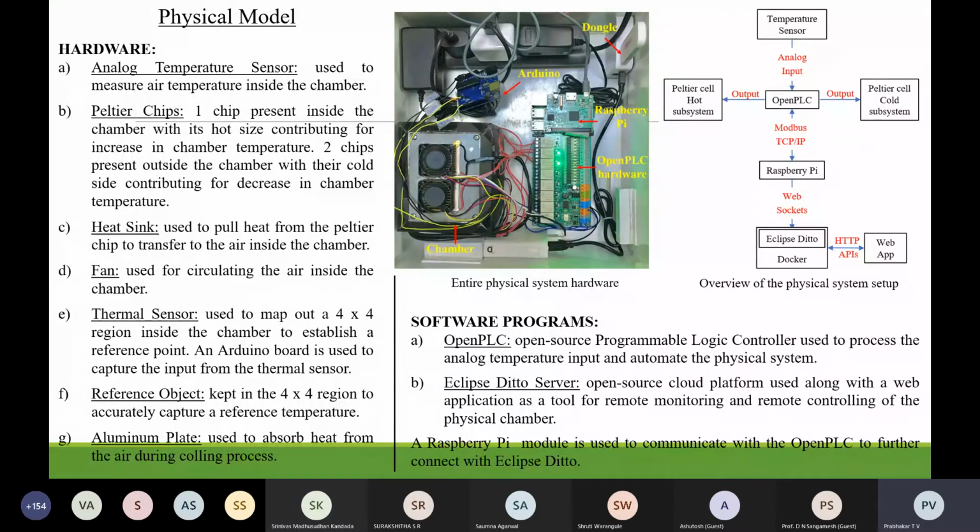That's one approach. The approach that I'm mentioning here is to use in industrial systems. They don't use Matlab for running actual PLC systems. You actually go out and buy a PLC. Now, OpenPLC allows you to download the PLC software, run it on something like a Raspberry Pi commercially available system. In fact, Raspberry Pi is available as a commercial version also for industrial applications. You can run it on that. And then once you open the GUI of the PLC, you can create all your control loops nicely, including timing, right? Because PLC gives you that advantage.